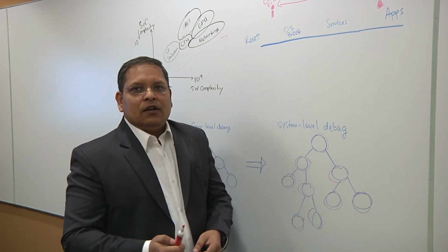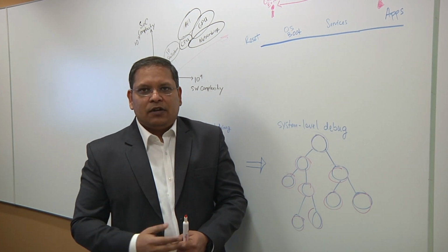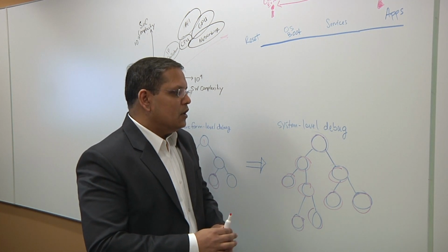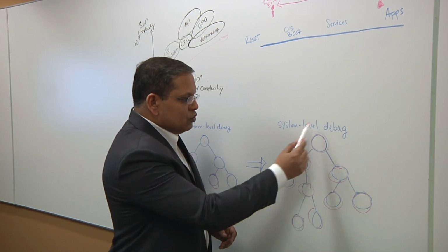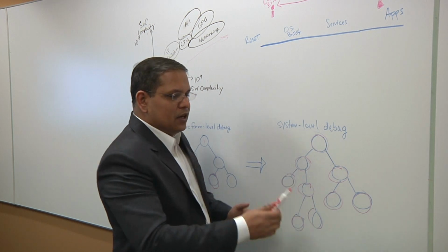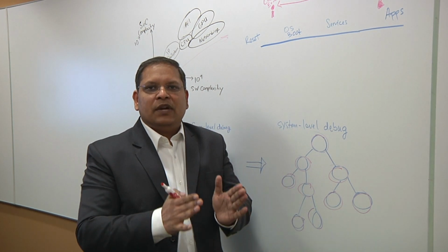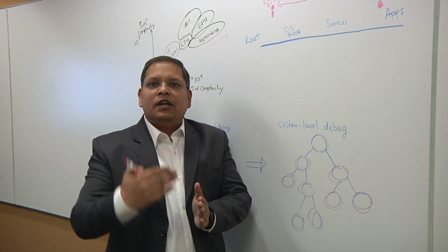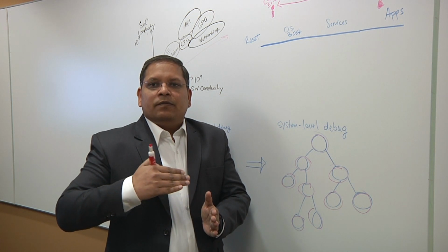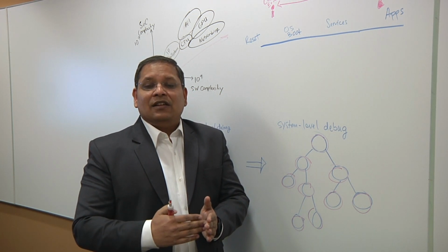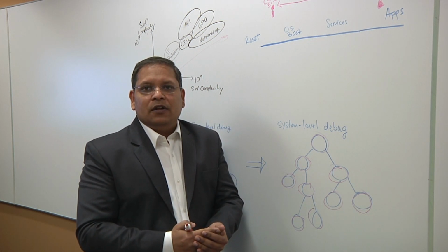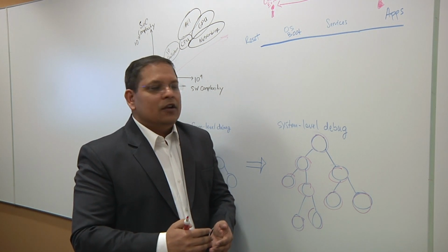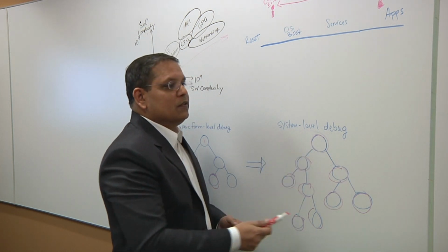Now, from there, we briefly touched upon deterministic debug, right? So that becomes a third very important aspect of it. Once you have found through this high level analysis that you want to focus your debug in a particular window, as I'm rerunning the test case to generate a waveform of that window, it is very important that I replay the design exactly the same way as the problem happened in the first run. So deterministic bug reproduction is the third key requirement for the solution that is needed for system level debug.